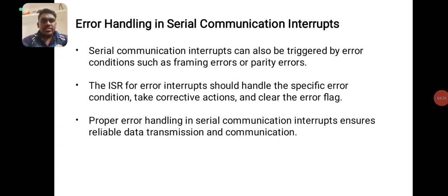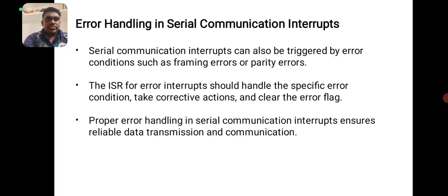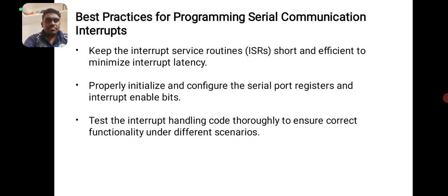Error handling in serial communication. We have learned about error handling in data transmission. Next, we have to learn about error handling in communication interrupts. Next, best practices for programming serial communication interrupts. Keep the interrupt service routine, ISR, short and efficient to minimize the interrupt latency. Otherwise, we have some tough conditions there.